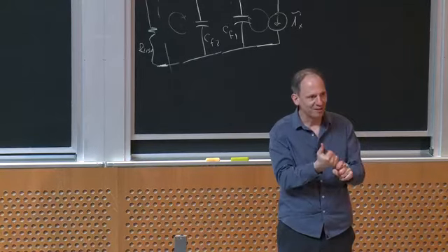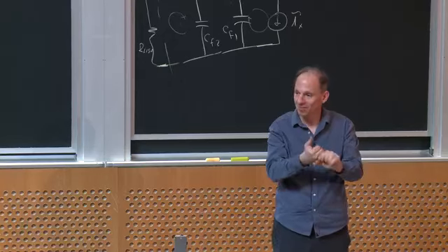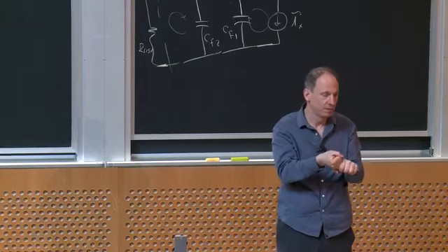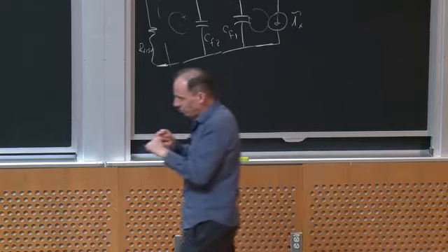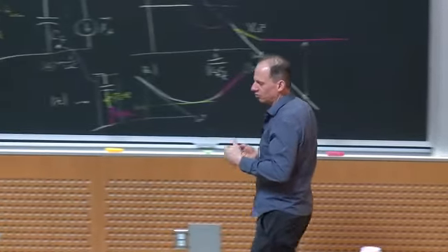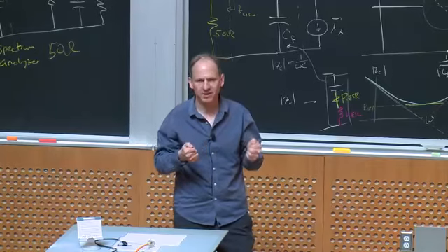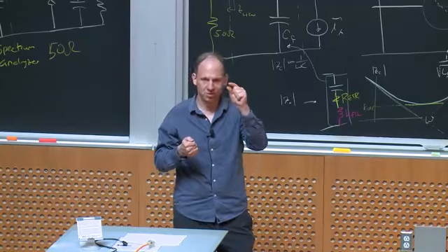So there's a lot of layout challenges and a lot of measurement challenges, and you just gotta be willing to dig through them, and eventually you'll get something. But when you're dealing with power supplies, you don't try to design something that's gonna pass the specifications by a few dB, by a small margin.